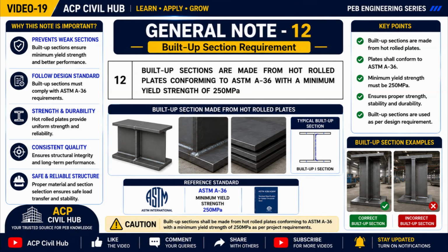According to this note, all built-up sections must be fabricated from hot-rolled steel plates conforming to ASTM A36 specifications. The material must have a minimum yield strength of 250 megapascals, ensuring adequate structural capacity for carrying design loads safely.